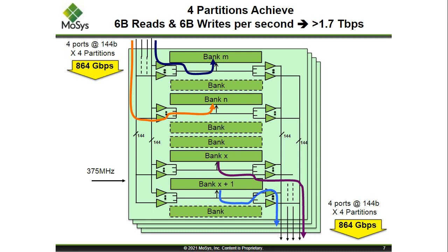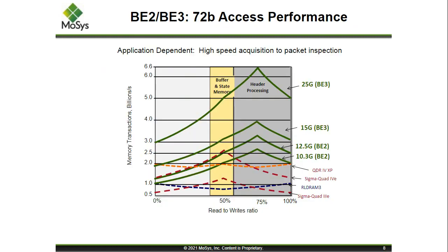So if you wanted to do 2, and in the larger devices 4, you can. So again, on the larger devices, that means with the 4 partitions, you can do up to 16 writes and 16 reads simultaneously in 1 TRC or 1 memory cycle. Again, what that leads to is, as the top points out, the header here, that you can get up to 1.7 terabits of bandwidth within the device itself. Again, we'll go through why this benefits things later on.